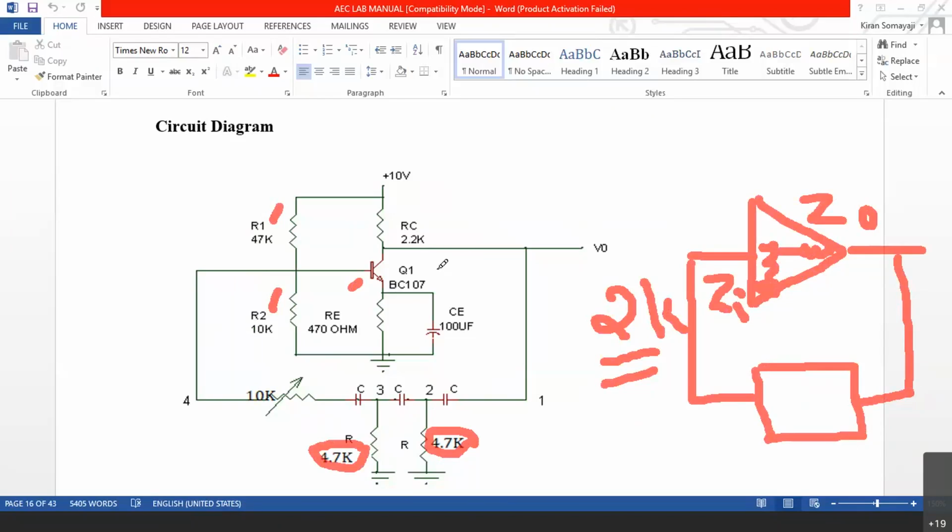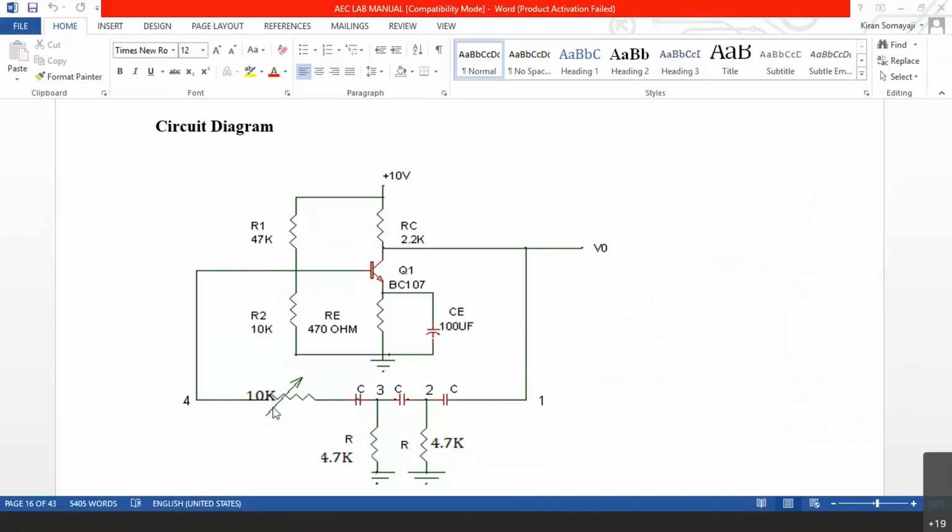So if 10 batches are conducting the experiment with the same transistor, you will have 10 different values of input impedance. Input impedance is a dynamic quantity that cannot have a fixed value. Now when we don't know the actual value of the input impedance, how do we fix the external resistance here? So the solution which we find in the lab is, we connect a potentiometer in series.